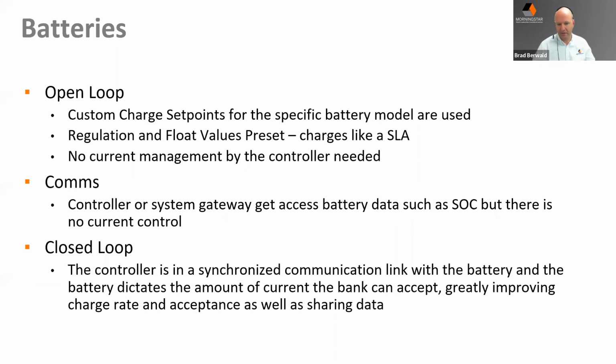What you'll see on upcoming products is closed loop integration. That would be where we actually have a communications link occurring between the controller and the battery, and where we are able to get feedback from the battery on what it wants to see, what its internal state of charge or temperature is determined to be. And we use that data in a synchronized relationship so that we can charge that battery with higher levels of current more accurately, and also use that state of charge data to make system sizing decisions.